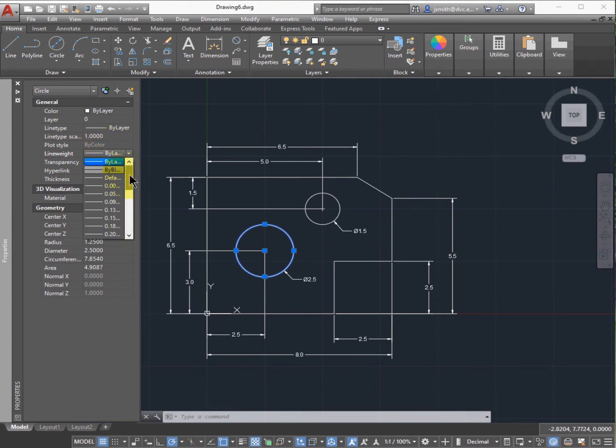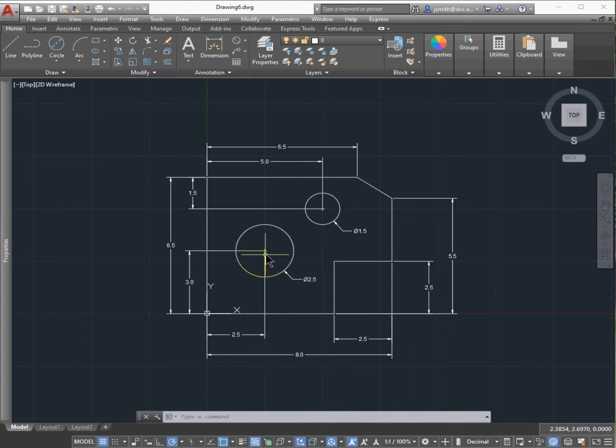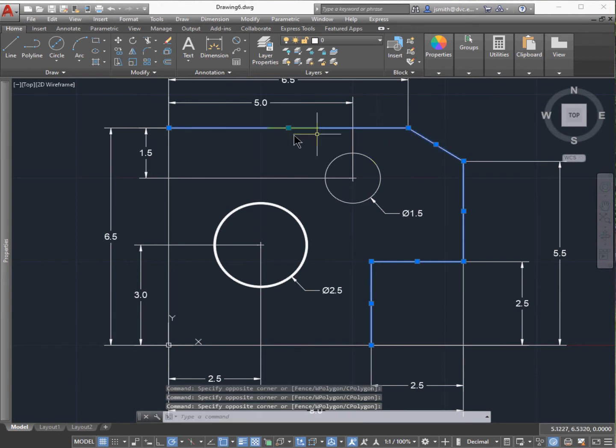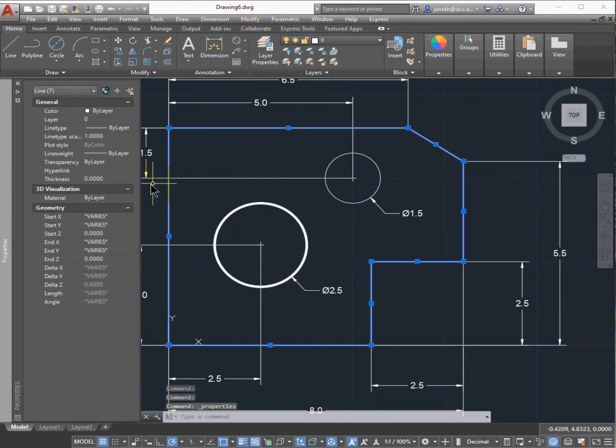So you want to put it, this is in millimeter, we're going to do it at 0.5, all right? And so you're going to have to try this, but what you want to do, right now nothing has happened, right? So if you come down to the right, make sure that the line weight tab is selected, and then you turn it on. This is the line. And so on the bar below, it's these 3 horizontal lines, and you select it, and that turns it on. All right, and so then I'll right click on it or hit Properties, and I'll do the exact same thing. So I'm going to go line weight, and I'm going to select 0.5.